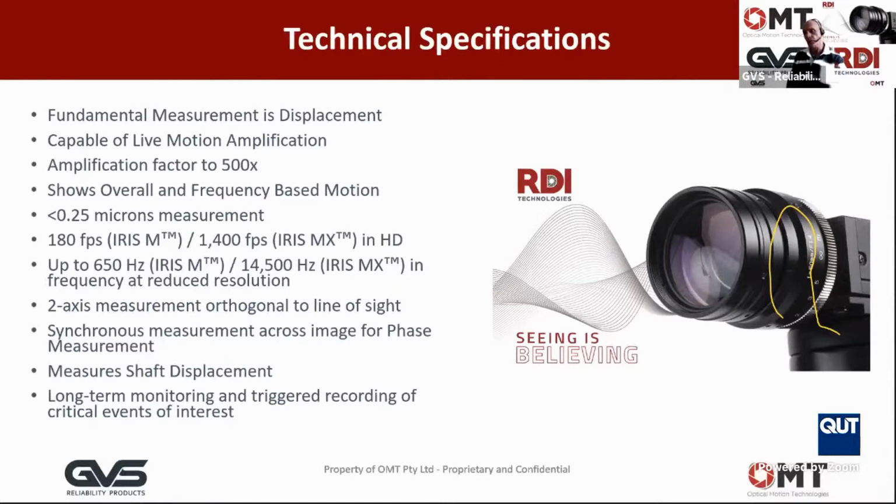So if we were to do an FFT of what we had acquired there, that would give us a maximum frequency on the FFT spectrum out to half of the 180 frames per second. So that's going to be 90 hertz that we would see as the Fmax on our spectrum.